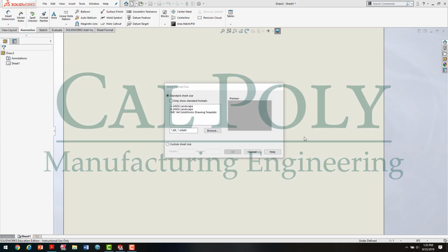Your first step when creating an engineering drawing is to select your title block template. Now, I've provided a title block template for you to download up on Polylearn, and the previous video, drawing number 1, shows you how to insert it as one of the standard sheets that you can pick by default. So I'm going to select the IME 144 SolidWorks drawing template, and press OK.